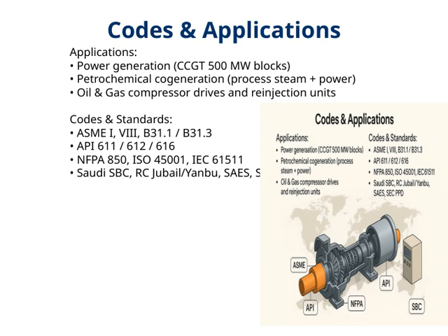We also align with API standards like 611, 612, and 616, which are specifically tailored for turbine and compressor equipment in the oil and gas industry. Beyond that, standards like NFPA 850, ISO 45001, and IEC 61511 guide our safety systems, occupational health, and safety management.